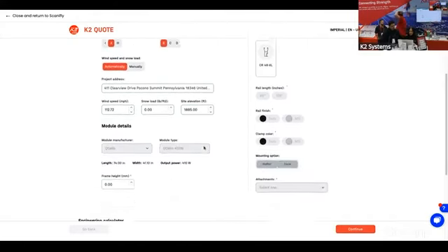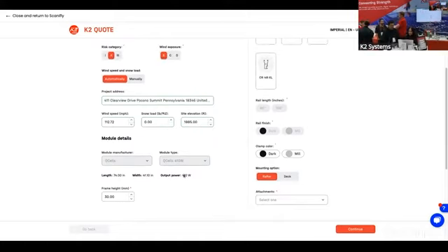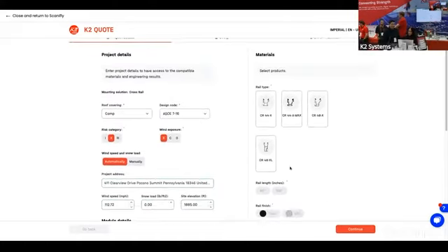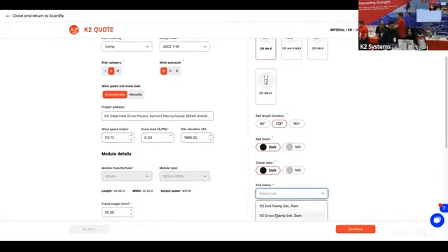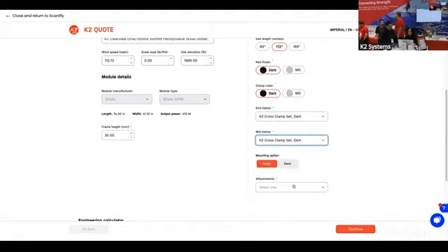So basically, we're gonna go ahead and put the frame height from the model selected back in Scanifly. This is gonna enable us the selection of the materials that we want to use in our racking installation, basically. So we're gonna go ahead and just select the materials of preference. And this is going to help us create little by little our BOM.